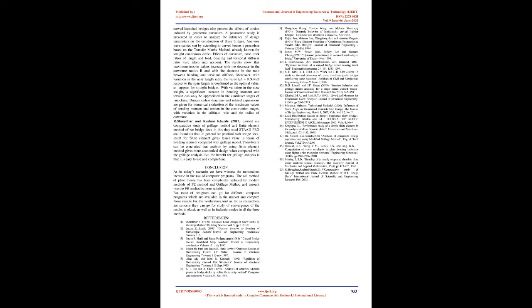Especially in the case of curved steel box girder bridges, non-uniform temperature distribution caused by solar radiation may lead to unusual load effects enough to damage the support or even topple the whole curved bridge structure if not designed properly. At present, it is very difficult to design bridges in relation to solar radiation because it is not known exactly how varying temperature distribution affects bridges, at least not specific enough for adoption in design. Standard regulations related to this matter are likewise not complete.